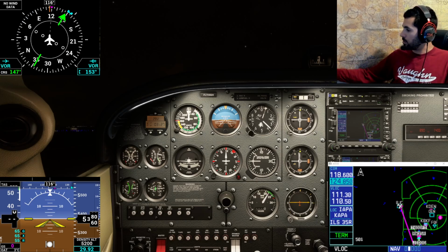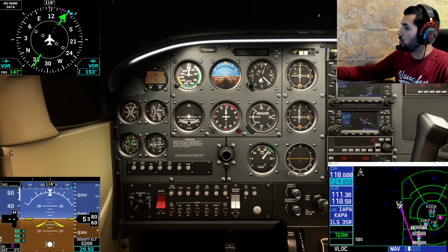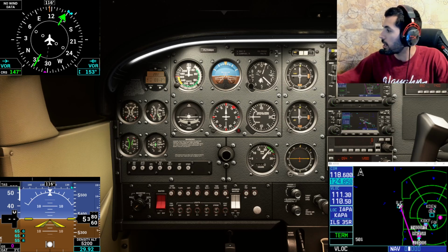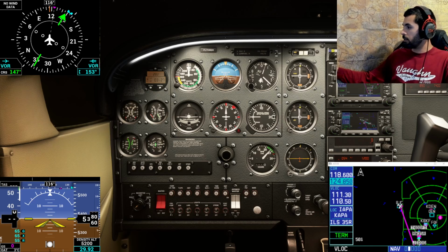And all I want to do is lean the mixture. The mixture's this little red knob down here. I can just pull it back, and you can start to see the tachometer start to rise little by little. We're just looking for max RPM, so wherever it drops, we're going to put the mixture back in. This is really just leaning for altitude. The less air, the less fuel we need. Getting about an extra 100 RPMs up there.